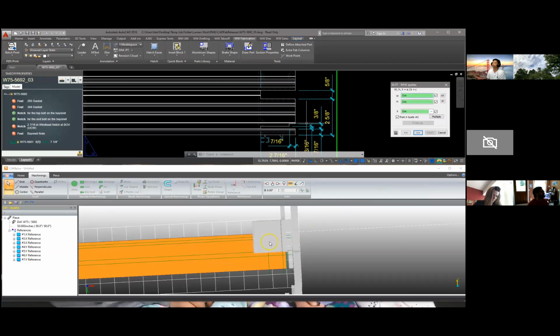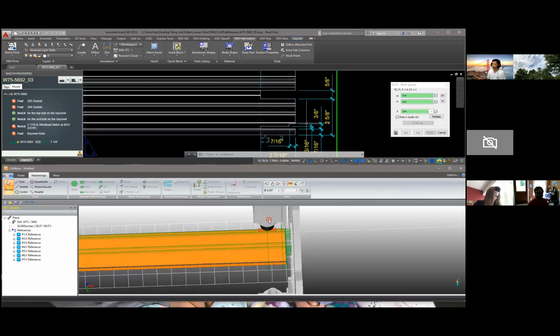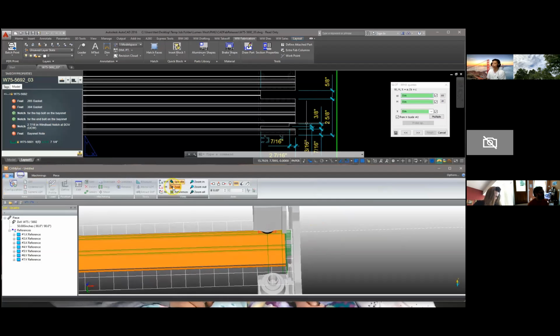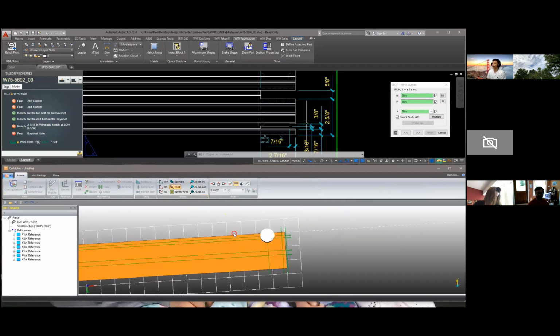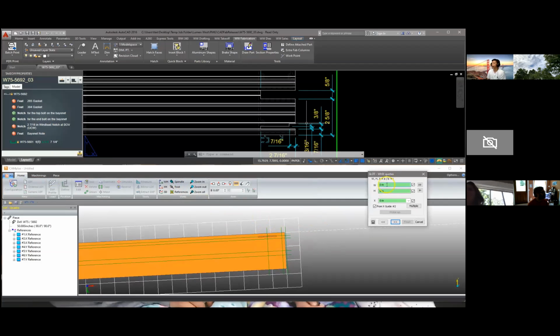As you can see, the spindle is in the way right now. You can rotate the part, or there's a function where you can turn off the spindle and the tool holders. Once we turn it off, now we can clearly see the slot located at the intersection point. So we can change our width, which is the in and out, right there. We can put the adjustment in there. So 0.188 divided by 2 is 0.094 to move it into the notch.